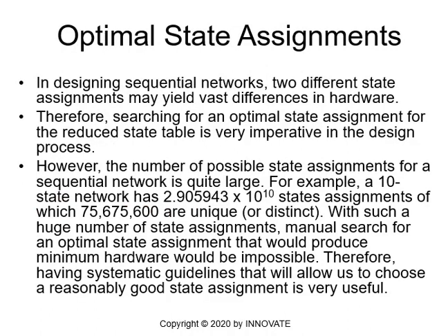Optimal state assignments. In designing sequential networks, 2 different state assignments may yield vast differences in hardware. Therefore, searching for an optimal state assignment for the reduced state table is very important in the design process. However, the number of possible state assignments for the sequential network is quite large.